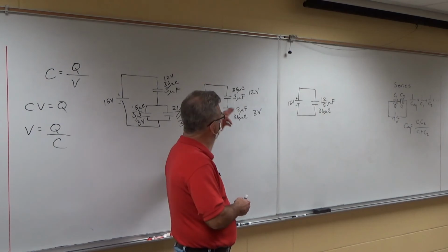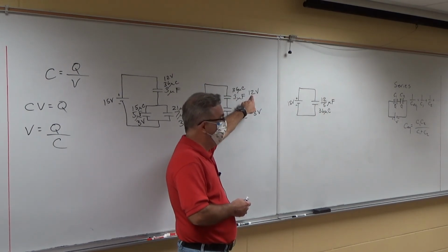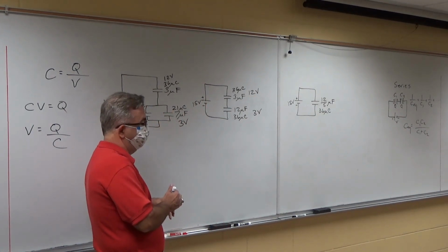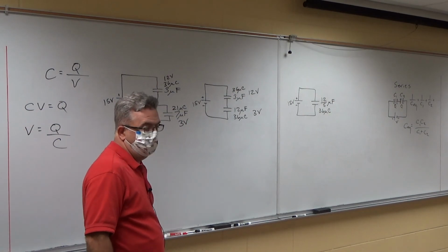So in series, the smaller cap will always have the higher voltage. In parallel, the larger cap will always have the higher charge.